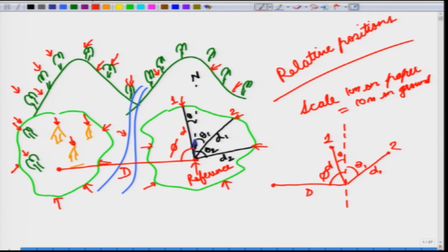So, you get the second reference on the piece of paper, and now you can start plotting the points that are being measured from the second reference. So, the first stage in surveying is to have a general view, so that you can figure out what is going to be your reference point, and if you require multiple reference points, what will they be.